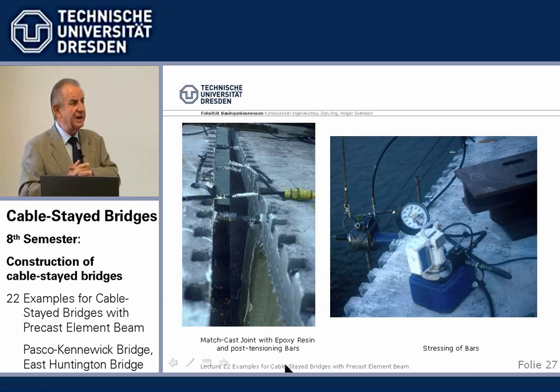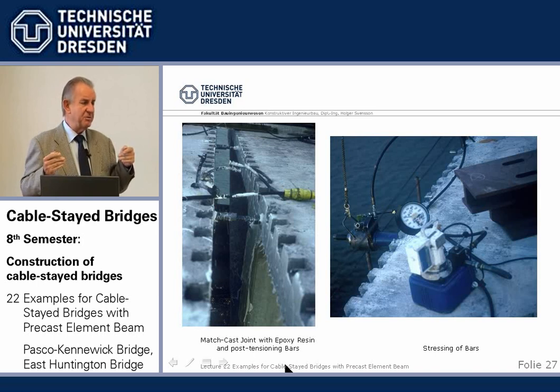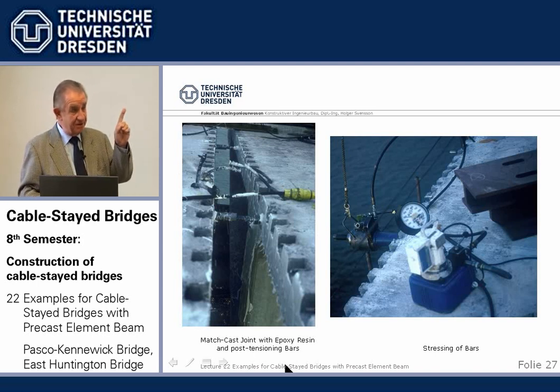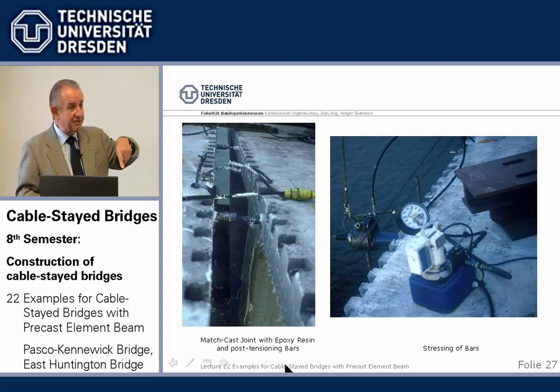Later on, people said, well, this epoxy and all that, that's expensive, especially the French. Jean Muller, for example, my friend, built the Key bridges in precast match-cast elements without epoxy. He said, what? Epoxy, we don't need it. Theoretically, yes, but I've been on Key bridges and others, and sometimes you can see the sun look through the joints where they do not fit as tightly, which means the water is running through.